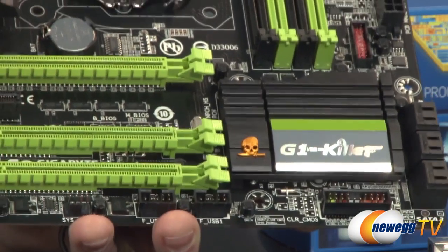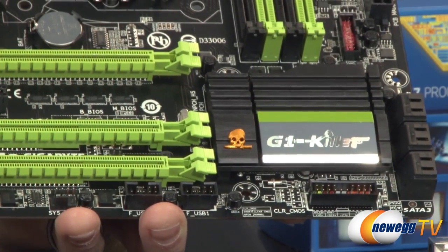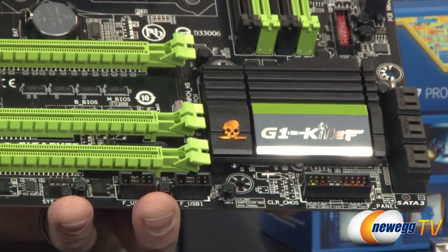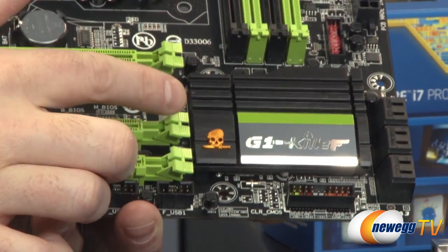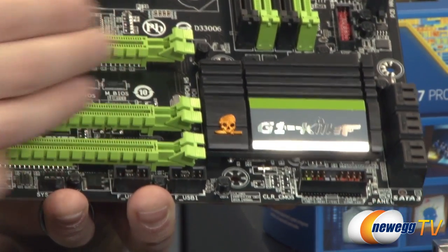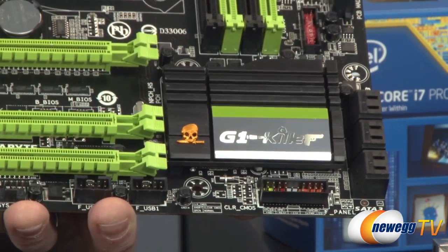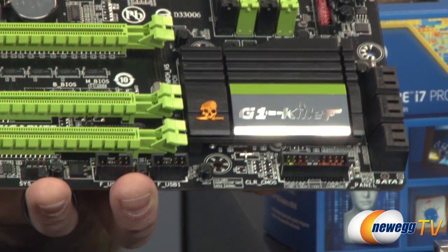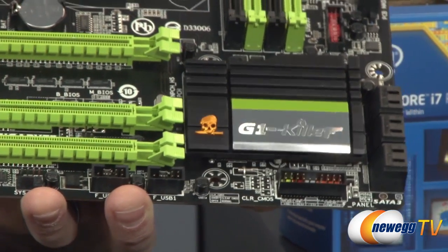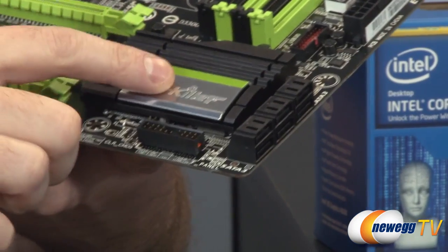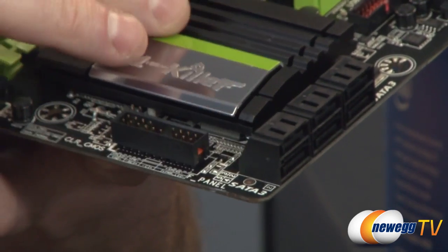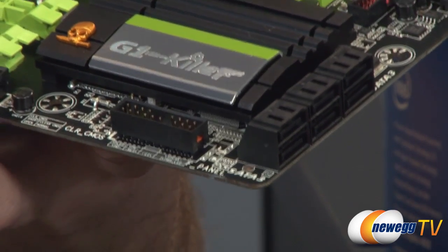If you go back a couple generations with Intel, for example, they actually had a few chipsets that they came out with. When Sandy Bridge first launched, which was their second generation processors, you had a P67 chipset, you had an H67 chipset, and then later on you had a Z68 chipset, and that led to a little bit of confusion from folks. Fortunately, they simplified things a little bit more. But referring to the chipset that's used in the motherboard and the characteristics of that chipset, often the chipset will control some serial ATA ports, and having what is known as native control over your serial ATA by the chipset will often give a little bit of a performance boost.